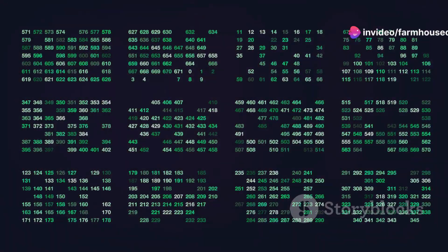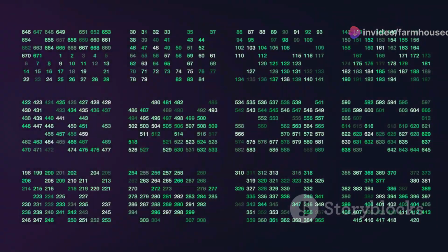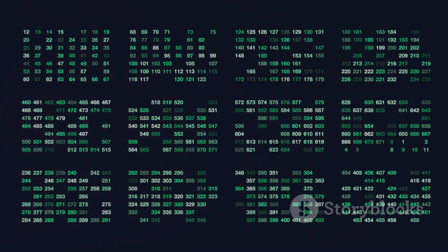Let's say the truth table has a 1 output for A equals 1, B equals 0. This specific combination will guide us in marking the K-map accurately. We mark the cell corresponding to A equals 1, B equals 0 with a 1. This step visually represents the truth table data within the K-map framework.